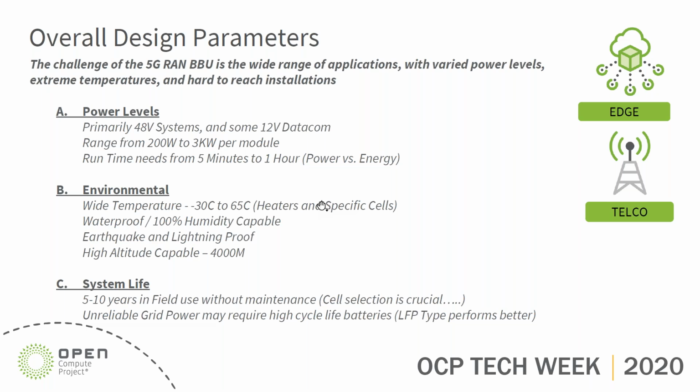Now, if we talk about, say, a UPS type of application, sometimes we're looking at maybe 5 minutes of runtime just before the generator might kick in. Or in a scenario where the customer may say, all right, well, we're going to shut down this tower because we're in battery time for a little bit too long now. So you may only need 5, 7, 8, 10 minutes to do that.